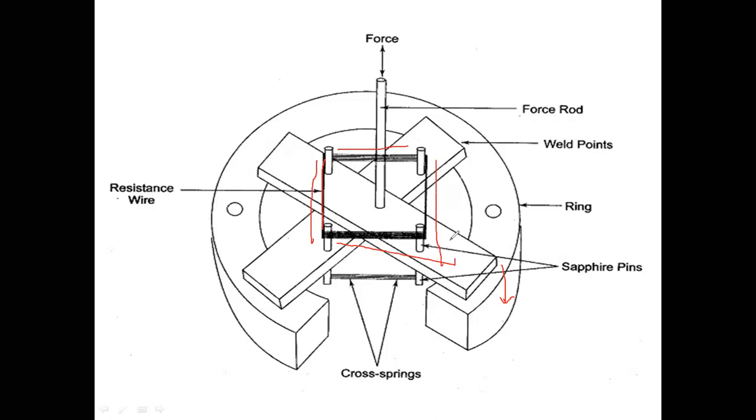See here, what I will do is take a material like copper nickel, chrome nickel, okay, copper nickel alloys. These are materials used to construct strain gauges. Copper nickel, chrome nickel, and nickel iron alloys are used to construct these strain gauges. Nickel is mostly used. Why?